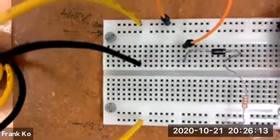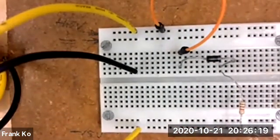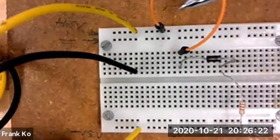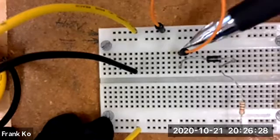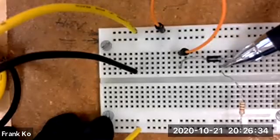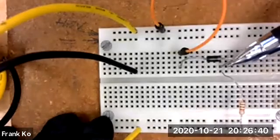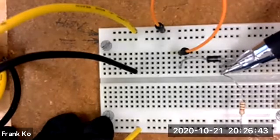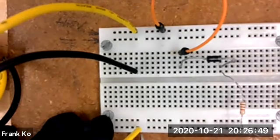All right. Can everybody see the circuit build? So from the secondary bus at the top, do you have a jumper wire going onto a tie point on the board? And at the tie point, do we have a diode? Is the diode set up with the cathode on the right-hand side, meaning it's pointing away from the secondary? Then the cathode of the diode is attached to a resistor, and the resistor is hooked up to the lower secondary wire right there. Okay, is everything built like so?